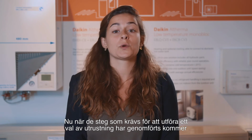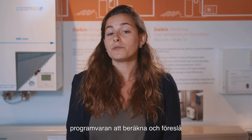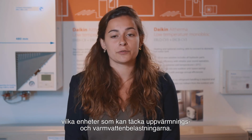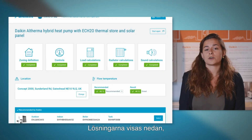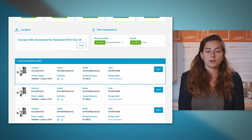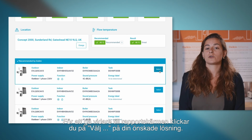Now that the steps required to perform an equipment selection have been taken, the software will calculate and determine which units are capable of covering the heating and hot water loads. The solutions are shown below, with Daikin's recommended solution at the top. To proceed to the report screen, click Select on your preferred solution.